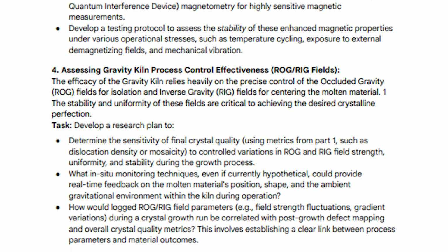Develop a testing protocol to assess the stability of these enhanced magnetic properties under various operational stresses, such as temperature cycling, exposure to external demagnetizing fields, and mechanical vibration.